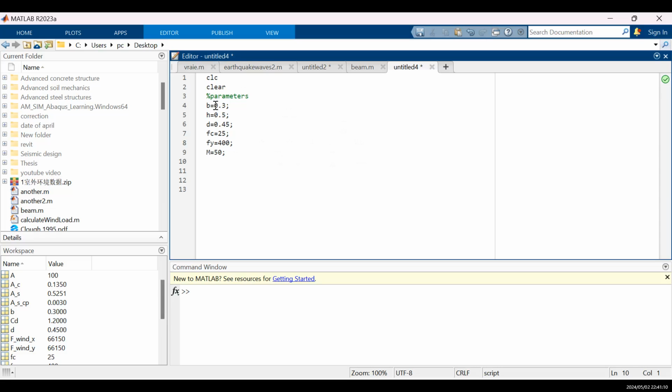So this is all the components that you have to have before you find out which reinforcements you have to use, right? The second step is that you need to modify the coefficients according to the Europe code. So you have to modify the safety factor for the concrete and also for the steel bars, right? I'm going to name it gamma.